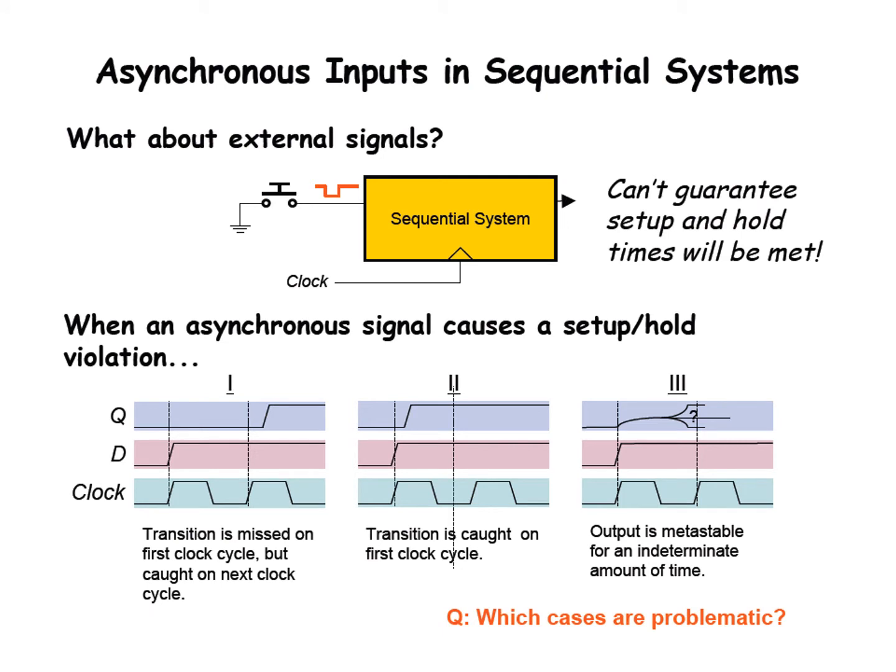The input signal, the button signal in the previous example, we are receiving from off chip. The clock is running like this. We don't know when this input signal will change, because it is not clocked by a flip-flop. It is just controlled by the human hand.